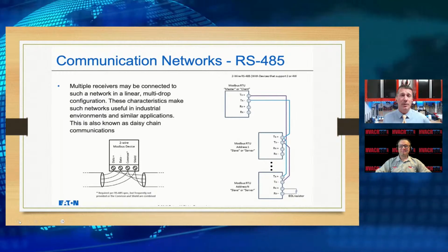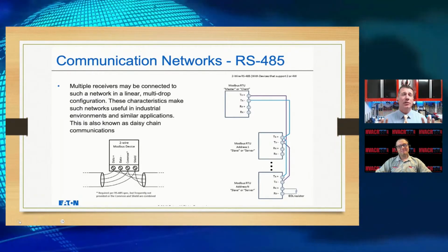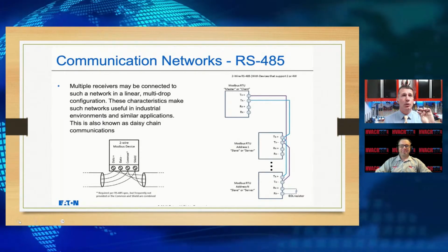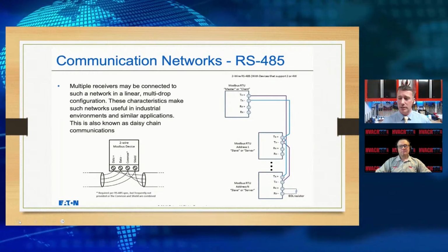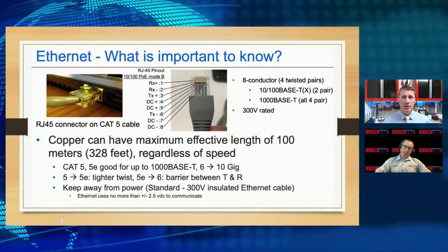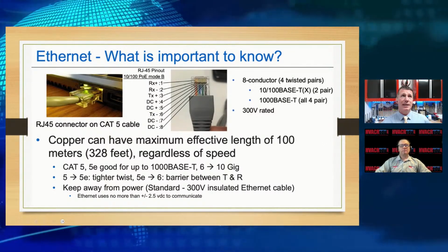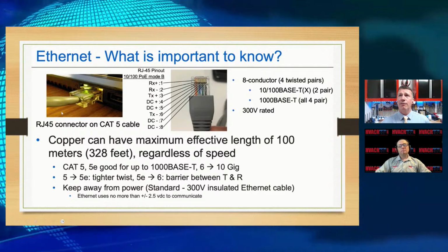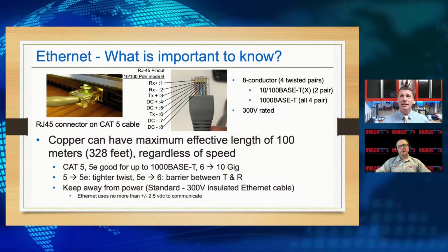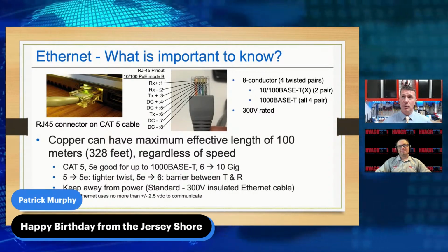So when we look at that communicating platform, it is very important for people to understand that as we look at all these different manufacturers, you're going to see a similarity. You're going to see in a lot of these a 4-wire system, two that we're going to communicate on and two that we're going to supply power. Now, we do get into some differences in the way we communicate, but it is all very much the same. So if we look at this basic layout of what we call an RJ45 communication, like Cat6 cables, a lot of different industries use a same or similar platform.